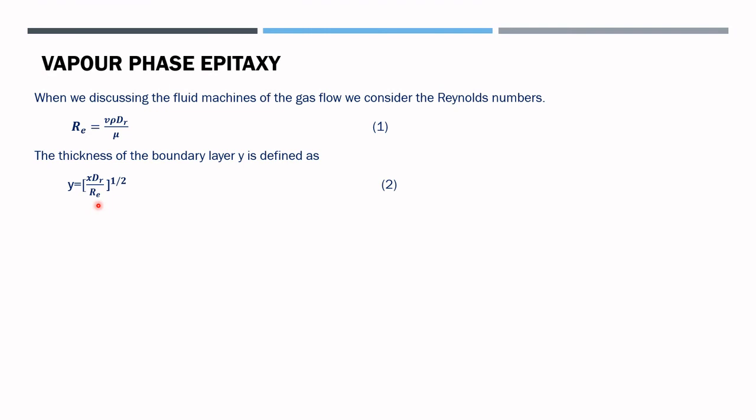From the figure, the boundary layer forms at the inlet to the reaction chamber and increases until the flow is fully established. Although fully established flows are not always encountered in the short length of a typical reactor, it is across this boundary layer that reactants are transported to the surface.